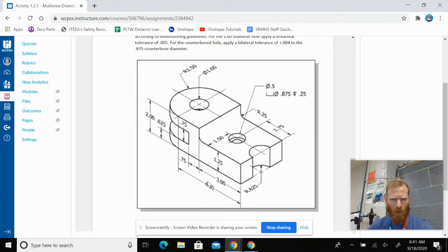But I do see right down here 4.5. That 4.5 is to the center point of this circle, but also the center point of this arch. Those center lines extended all the way out beyond the arch means that's the center point for the circle as well as the arch. I've already gone 3, so I need to go 1.5 inches more to get to the center point of the arch. And then our arch has a radius of 1.5, so from the center point, I need to go another 1.5 to get all the way out to the end. So that gives me 3 inches.